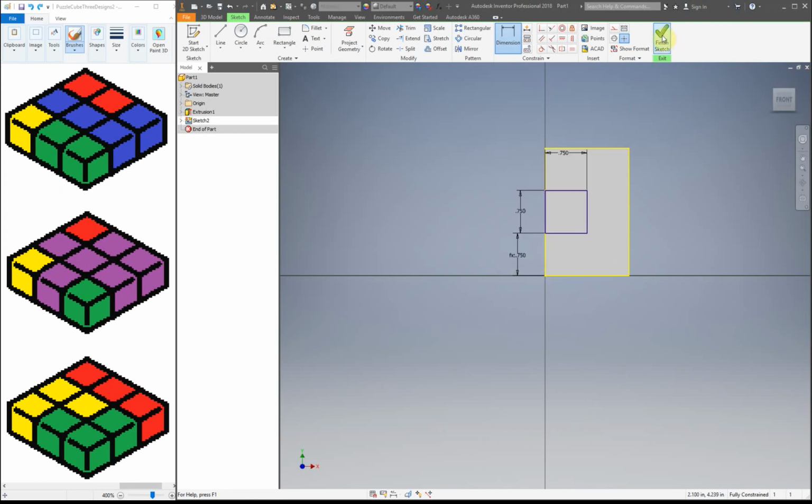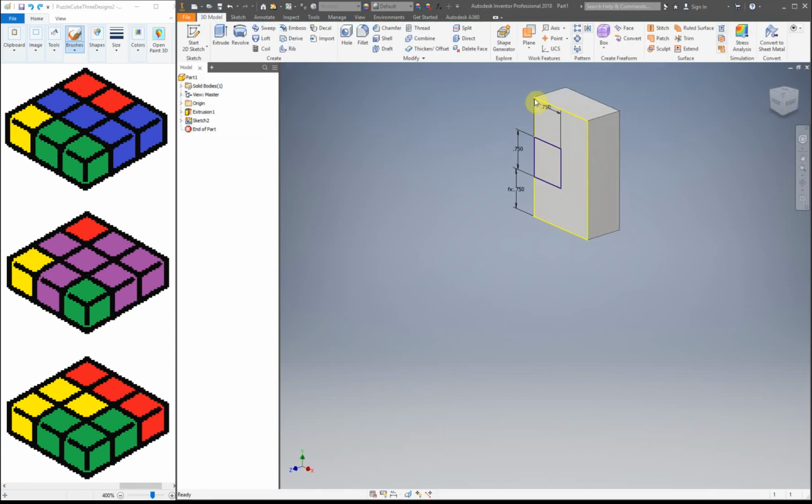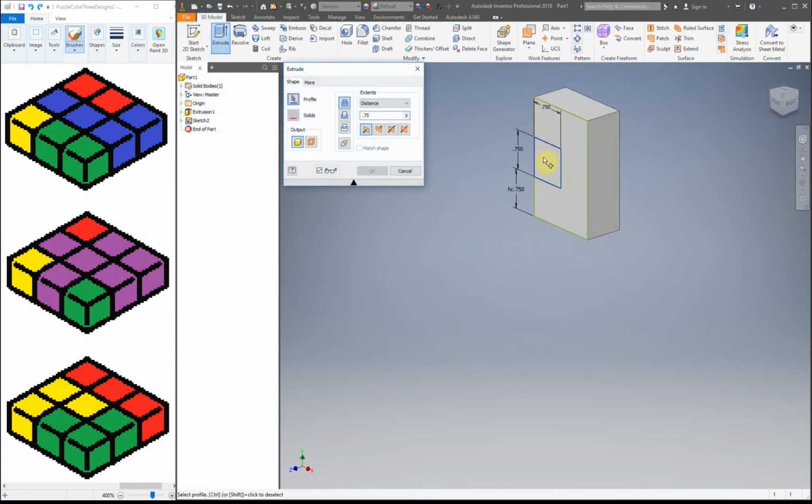So now that I have this little chunk that will be a different color later on, ready to be removed, we can finish our sketch, extrude, and click this part. You can see before it picked it automatically. Now since we have this C section and that one block, you got to pick which one. And I want to use cut.